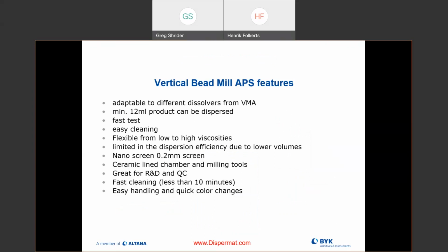Okay, so here are some of the benefits. Obviously, very adaptable, goes on all of our disc formats, very quick, can do small volumes, very quick to clean. I can use this for a very broad range of viscosity, so I'm not limited to just either low or high. So it's very nice for many, many different viscosity ranges. I have an ability to mill down into my primary particle size, even nano. Again, ceramic components available, and very easy to handle. And again, it's more for your R&D and QC lab, not really for your pilot or manufacturing.